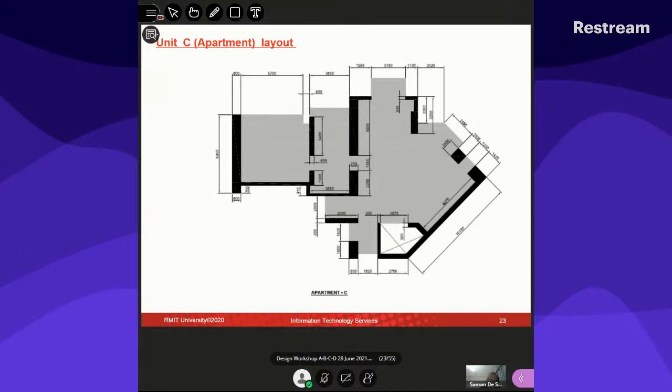Now I'm just asking, can't we span this one in this direction? You can, and then you have to see what is around here. There may be a slab, because this is where you are entering the house, or somewhere. Just have a look. If not, what you have to do is have a line in blue color or so, and identify a small beam going from there to there.